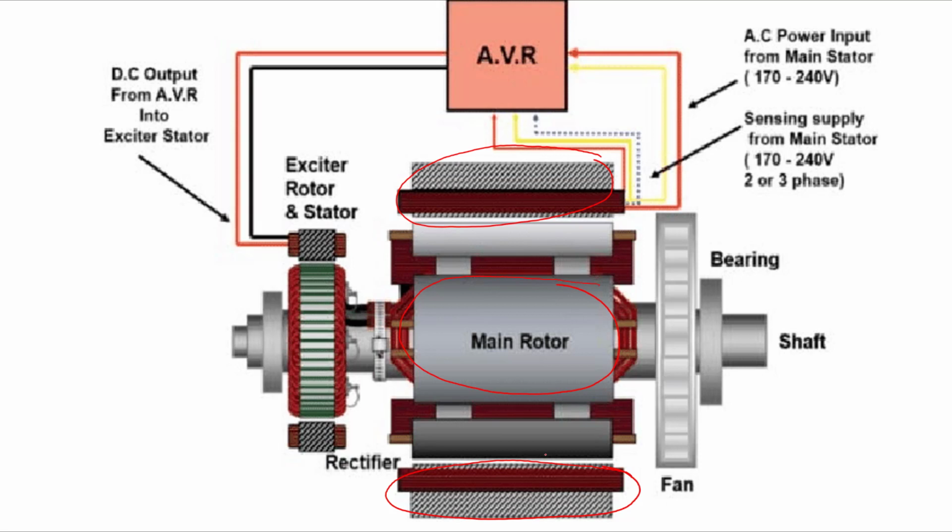But in case of a DC generator, as it is rotating, as we put the armature winding on the rotor, we put the commutator circuit or commutator segments, which in fact help us rectify the voltage, right? So we get a rectified output, that is DC output or DC voltage, okay?